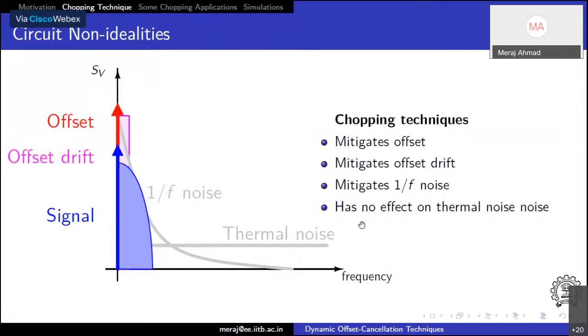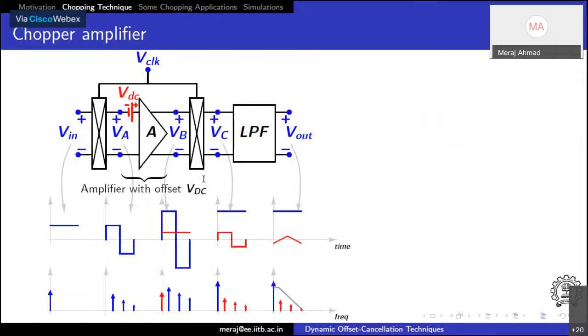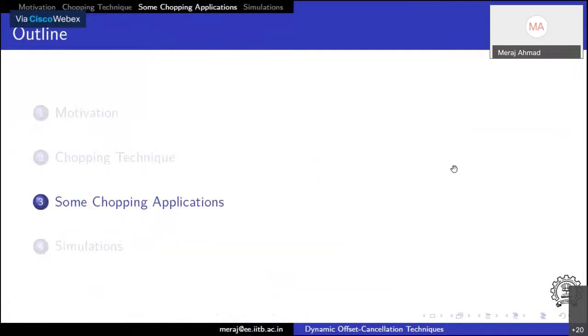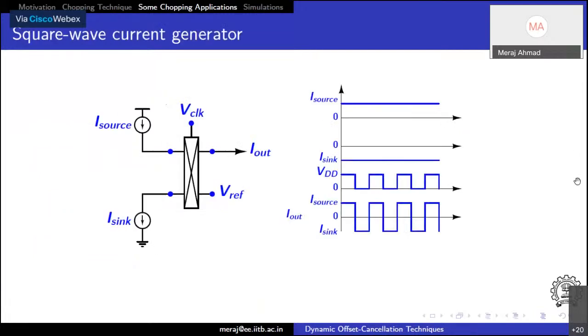This chopper is exactly how a mixer is implemented, but we are using a square wave in the mixer. This can also be a sine wave. So the simulation setup we will see today is equally applicable to simulating some RF circuits, like mixers. The same chopper can be used in various other places, which we'll see now.